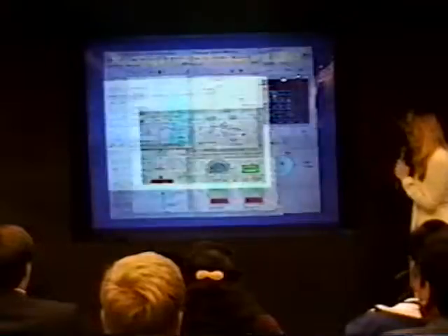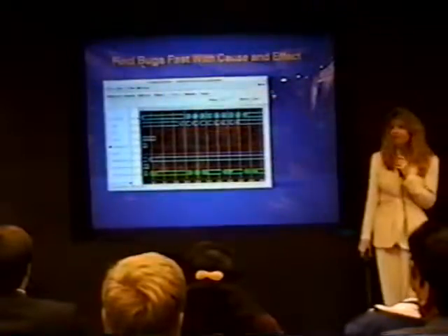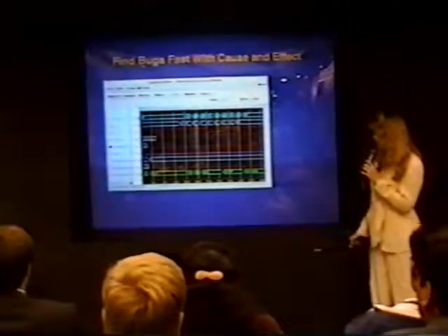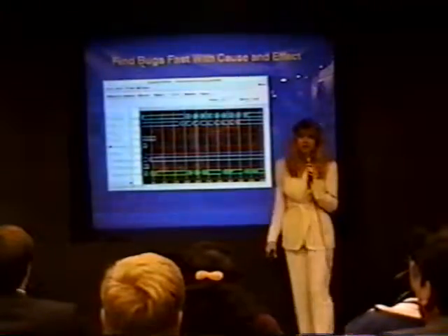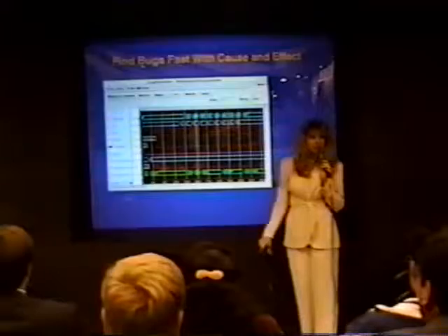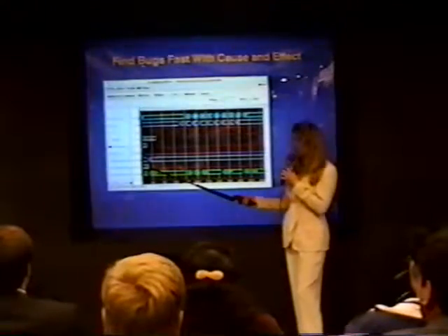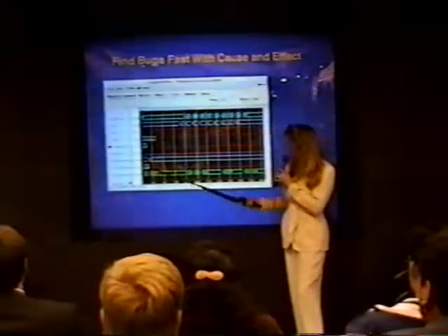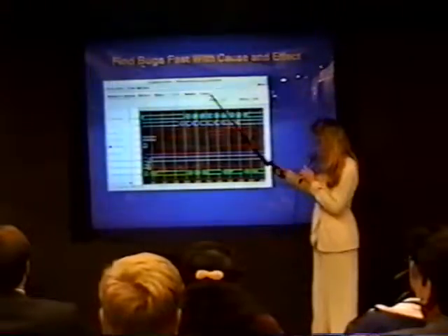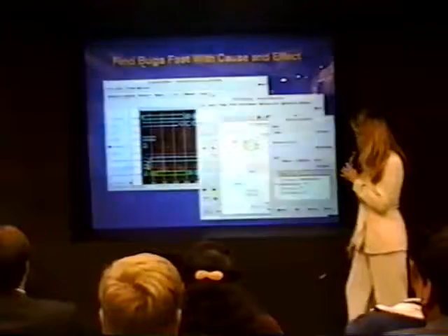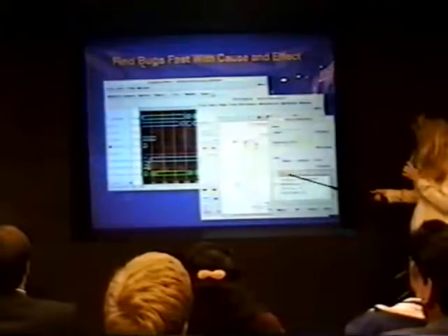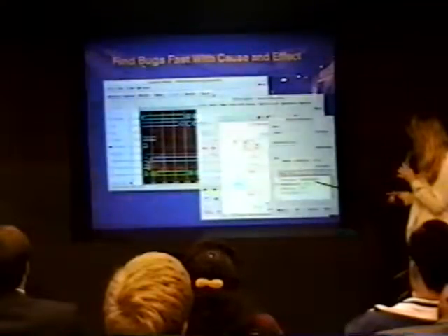With Visual HDL, you can efficiently trace every signal in your design during simulation and bring up its history anytime you wish. If you want to know why a transition occurred, with Visual HDL's cause and effect feature, you just select the transition, click the cause button, and the system will tell you the exact line of code being executed at that point in time.